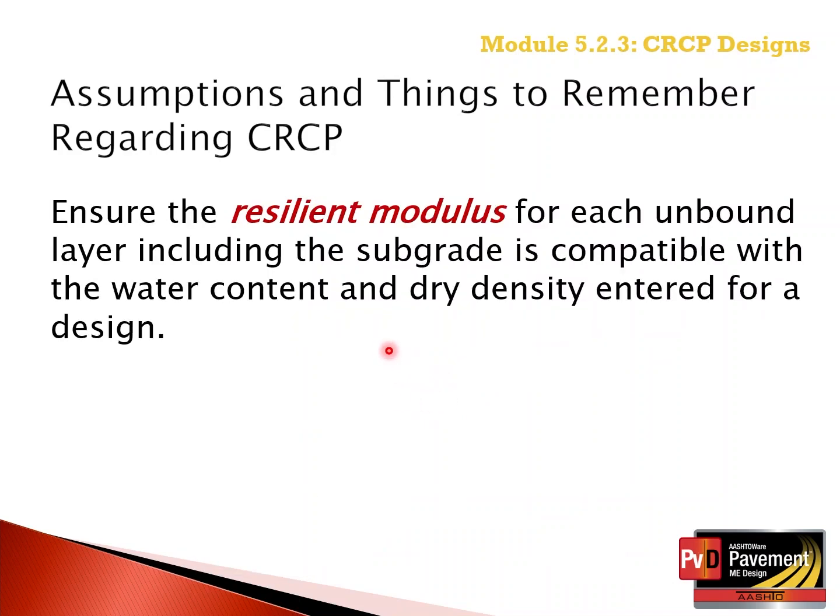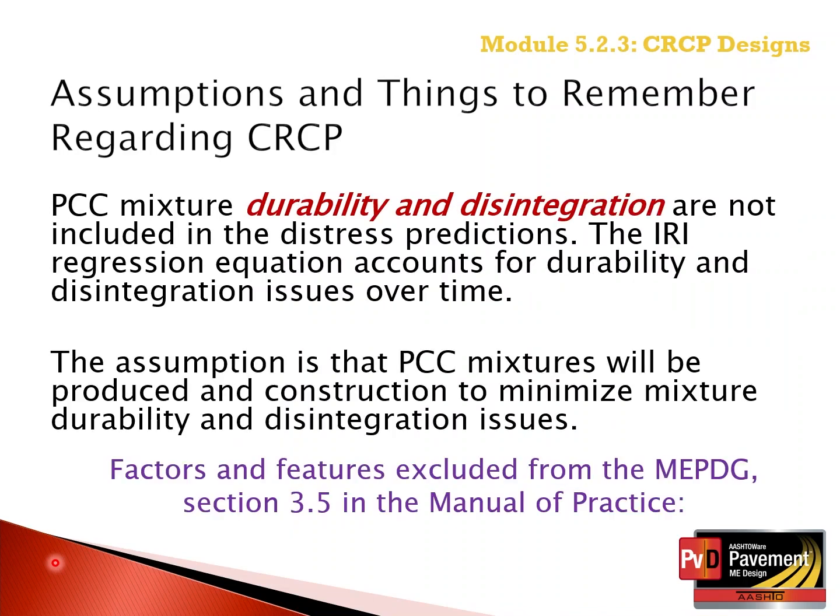Remember from Module 4.4.1 on subgrade soils and Module 4.4.2 on aggregate base materials, the resilient modulus of any unbound base layer should be compatible with the water content and dry density entered for a specific design. Just like for concrete, on strength versus modulus, we need to have input compatibility for the different layers, i.e. resilient modulus related to the water content and dry density of the material.